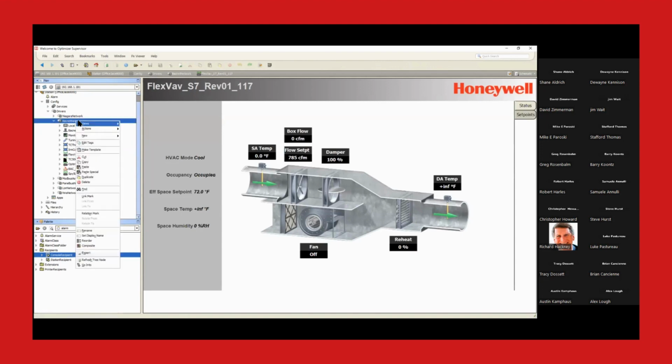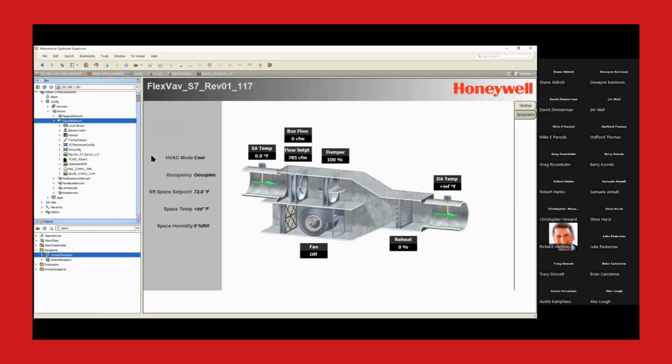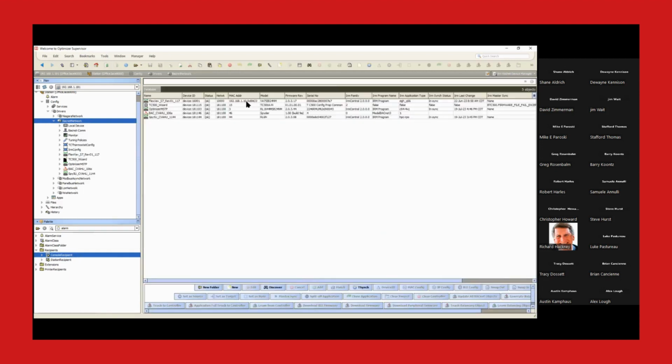If I go back to that BACnet device manager view that I was just looking at, there's nothing on this view that would tell me, other than the part number, that I'm talking T1L. I happen to know that I'm not talking T1L, I'm talking BACnet over IP over RJ45. But if I took my RJ45 connector and plugged it into a T1L adapter and did a discover, this is what it would see. It would see a BACnet IP controller. That help?